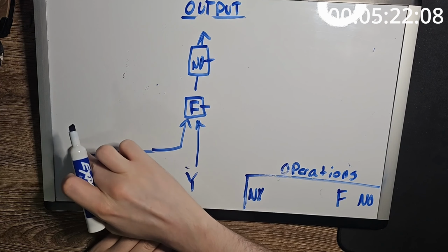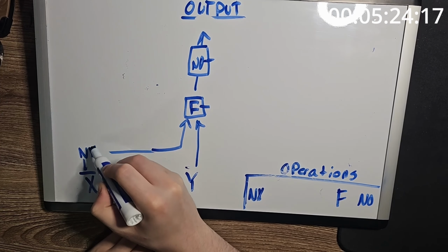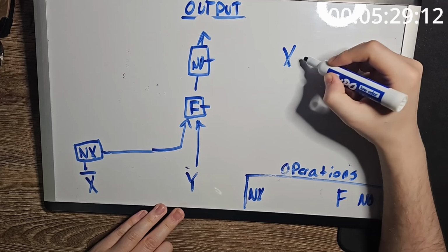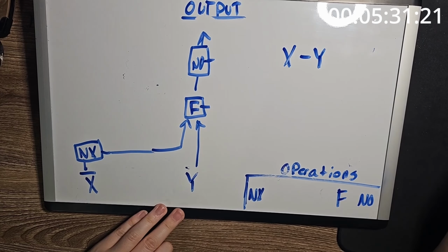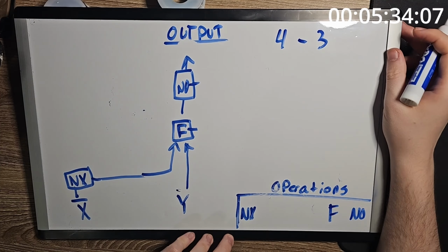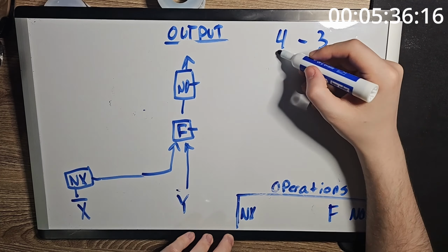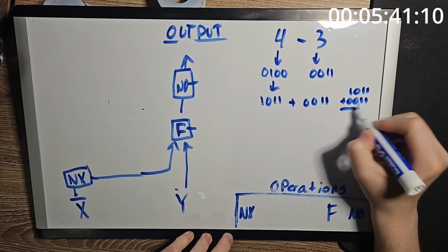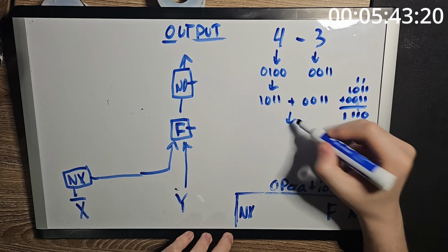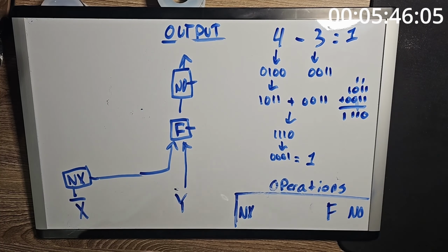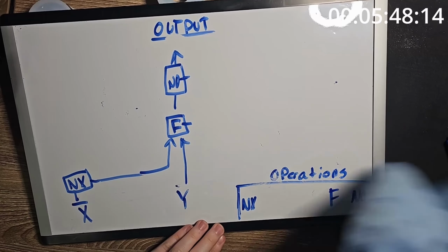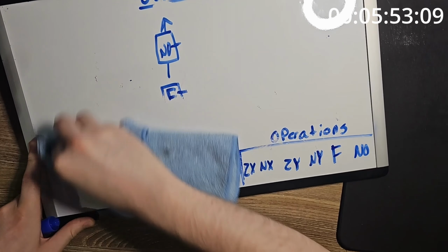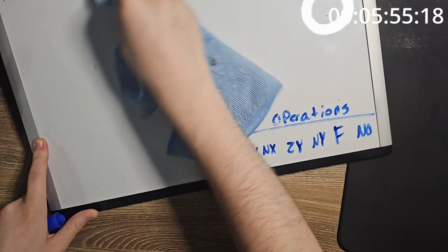We can have it not inverted or inverted. With these 2 new bits, if we turn all of the bits on, we have unlocked the X minus Y. In a nutshell, inverting a positive number will turn it into a slightly off negative number. This is because for a number to be positive, the leftmost bit needs to be a 0. Now if we add a negative number to a positive number, we get a subtraction operation. Simple as that. Now, we actually add a not Y operation, and then we can do a Y minus X if we turn the NY on instead of the NX.